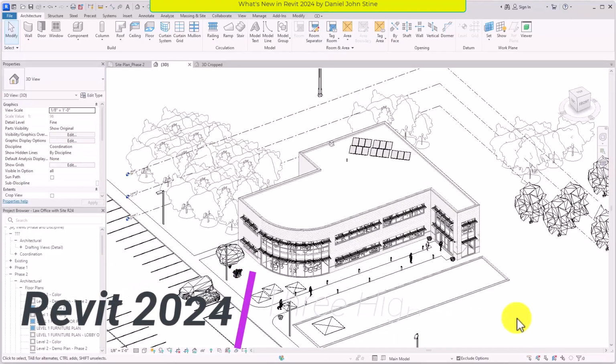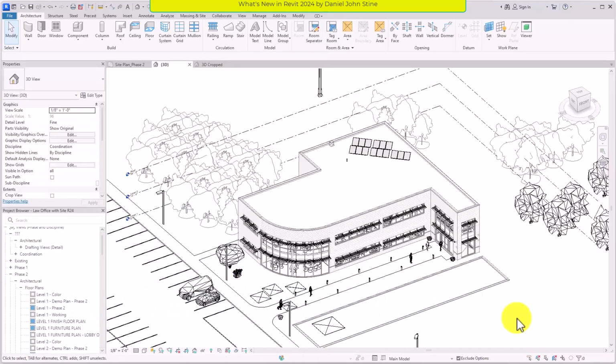Now I want to share 3 of my favorite new features in Revit 2024. The first one has to do with the early energy modeling workflow, either going from Revit to Insight or Revit and using its systems analysis tool, which uses OpenStudio and EnergyPlus locally. One of the challenges that we have sometimes is when we let Revit automatically create the energy analysis model is that it considers the entire project, and the only filtering option really is phasing or the elements room bounding option, and both of those can be destructive in a typical Revit design and documentation workflow.